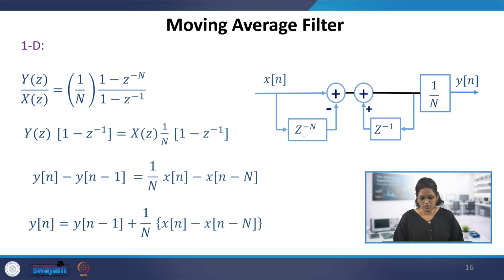So what is the function of this filter? It's taking N samples, averaging them and giving the average value. That N sample window can be slid over one sample at a time, or N samples at a time, whatever you want. Basically one sample at a time, then take the next window of samples and average it.